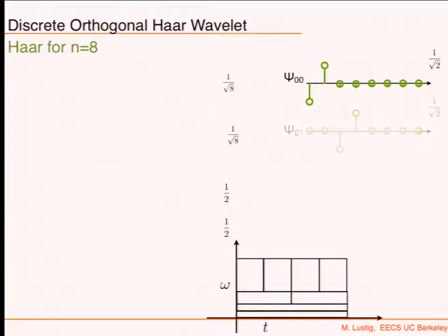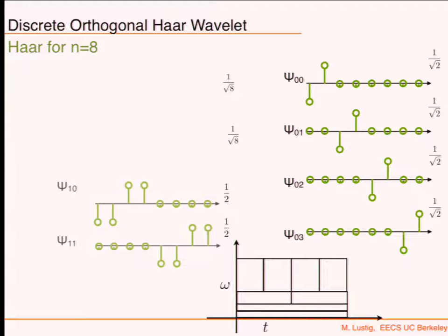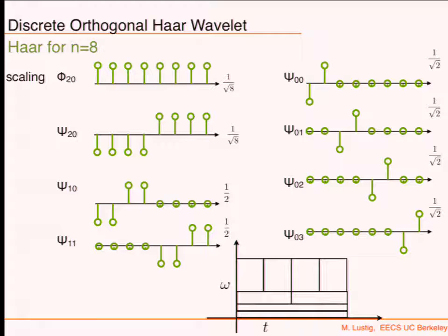Okay. So the one thing that we talked about last time was what happens when you have orthogonal Haar, and how is the mapping between where these occur in time and frequency, the frequency tiling of those Haar. And if you notice, this is the fine scale Haar wavelet. So they're localized.